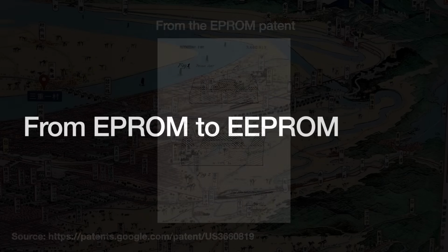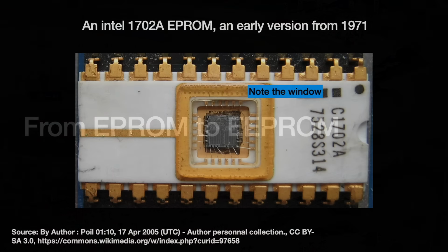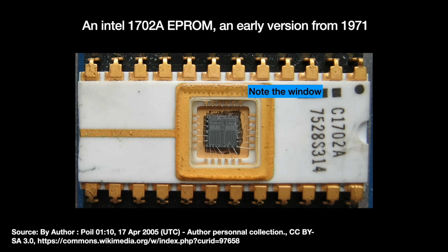One of the challenges of making a workable memory out of the floating gate transistor is how to get the electrons back out of the floating gate, a process formerly called erasing. Erasing the data from the EPROM required you to shine UV light directly onto the chip for 15 to 20 minutes through a quartz window. Cool at first, but over time it got a bit old.